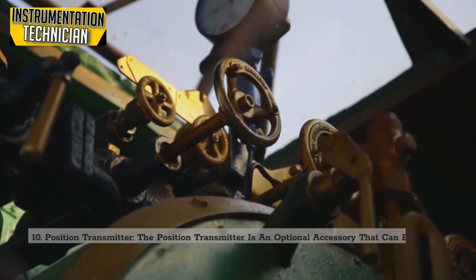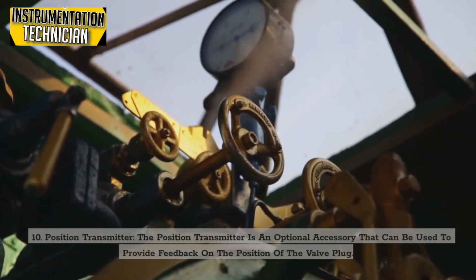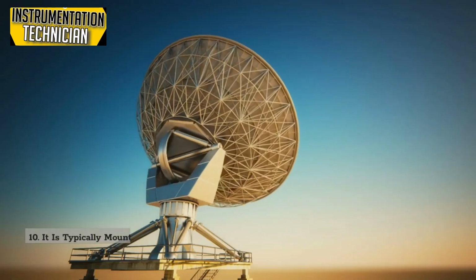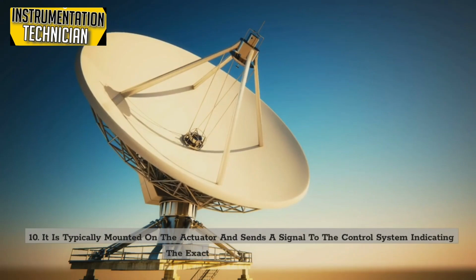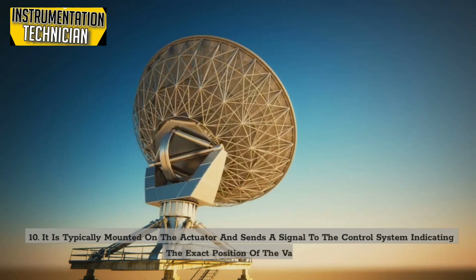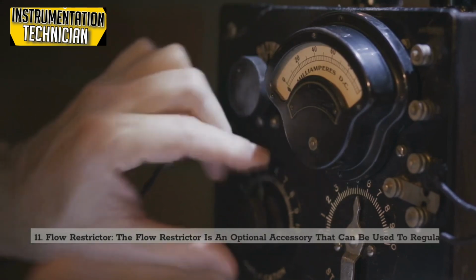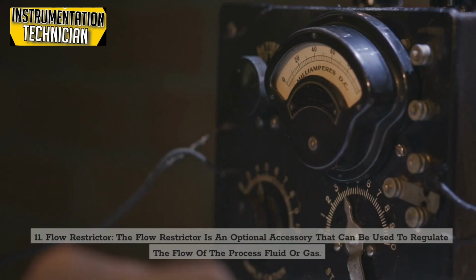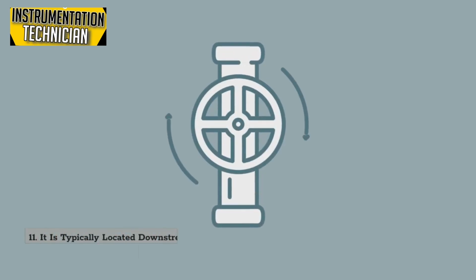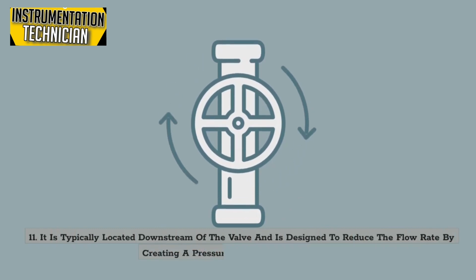The position transmitter is an optional accessory that can be used to provide feedback on the position of the valve plug. It is typically mounted on the actuator and sends a signal to the control system indicating the exact position of the valve. 11. Flow restrictor. The flow restrictor is an optional accessory that can be used to regulate the flow of the process fluid or gas. It is typically located downstream of the valve and is designed to reduce the flow rate by creating a pressure drop across the valve.